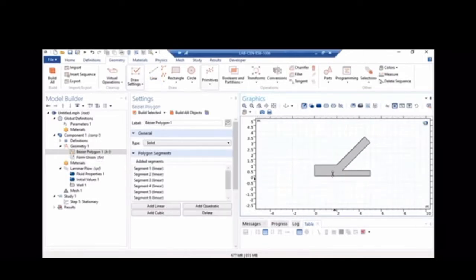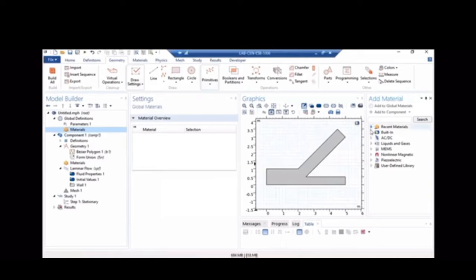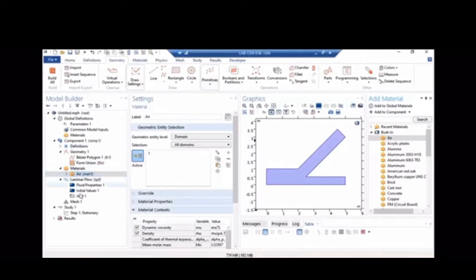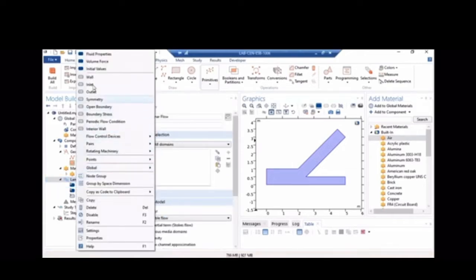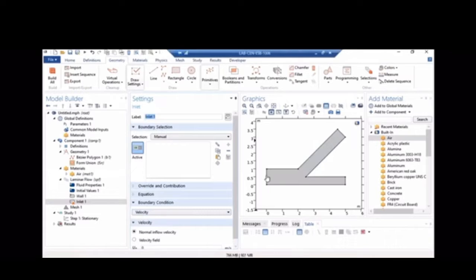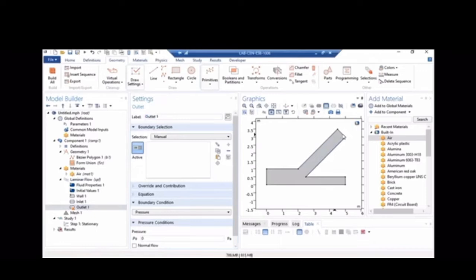Right click to form the geometry. Now I'm going to zoom in and adjust. As you can see here, we'll have to add the values for the inlet. Obviously choose air. Here you can see the fluid properties, inlet. Now this value is going to be 0.02, and then complete. Now you go to the outlets. Now my friend is going to continue explaining the mesh part.